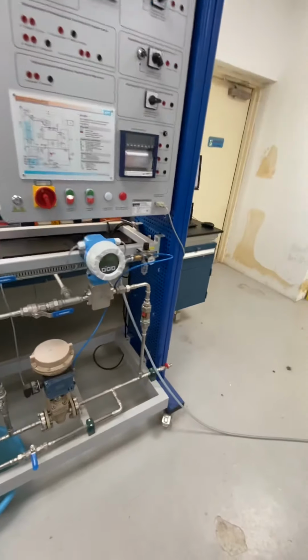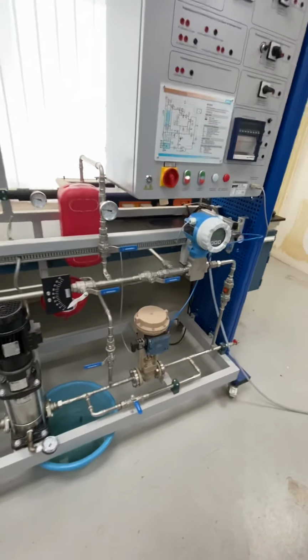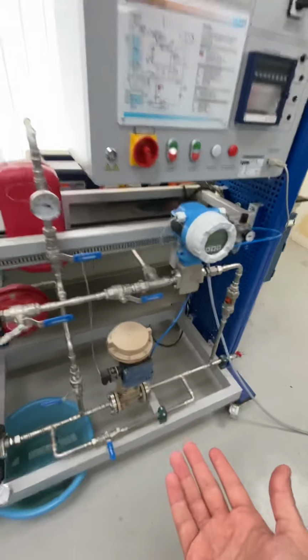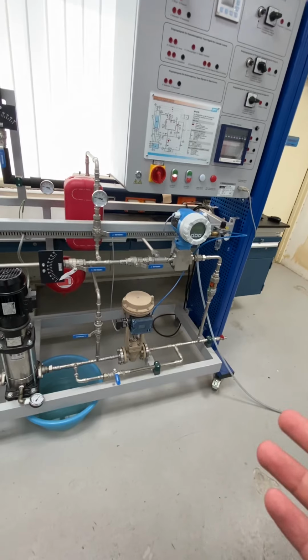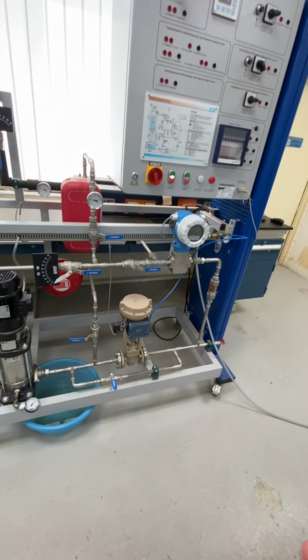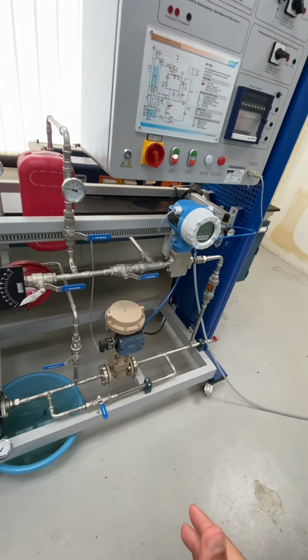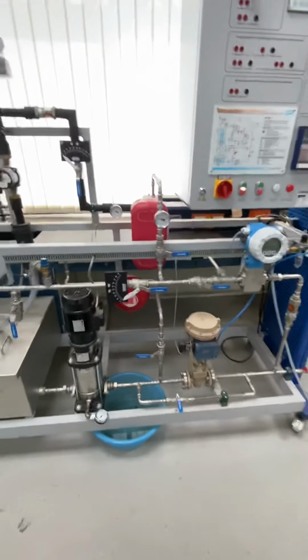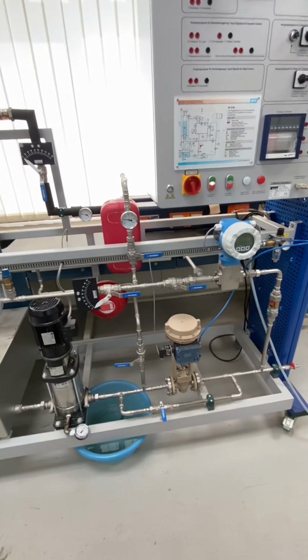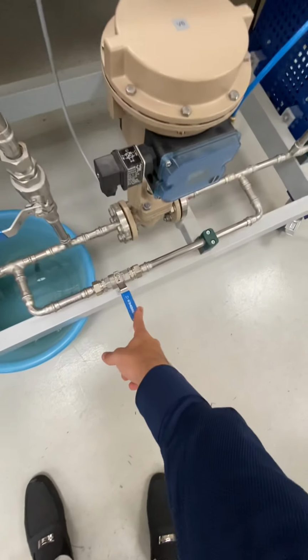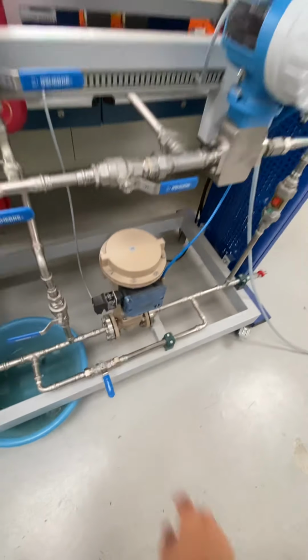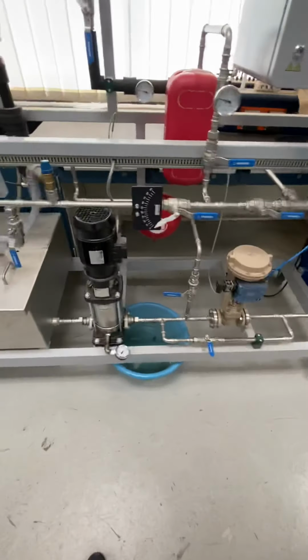So the change that will happen in this scenario is that the air supply to the control valve will stop, and that will return the valve back to its original position, which is a fully closed position. Now if the valve goes to a fully closed position, what's going to happen is that since this valve is closed, and the bypass valve and the automatic control valve are closed as well, the flow rate will stop through the system.